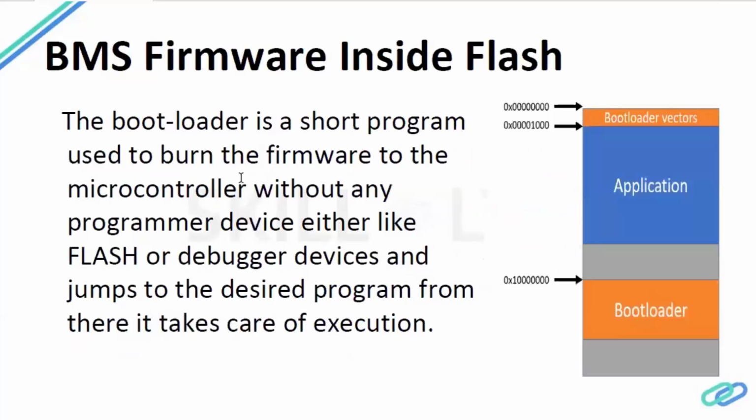Okay, now let us suppose we are using a microcontroller unit like an ARM Cortex, because you might be familiar with the architecture. There is an architecture called the ARM Cortex series of microcontrollers or microprocessors. 99% of embedded devices, whether mobile phones or electric vehicles, use the ARM Cortex-M series microcontroller. In the ARM Cortex-M series microcontroller, there would be some flash memory inside the microcontroller unit. They might have 512 KB or 1 MB of flash.